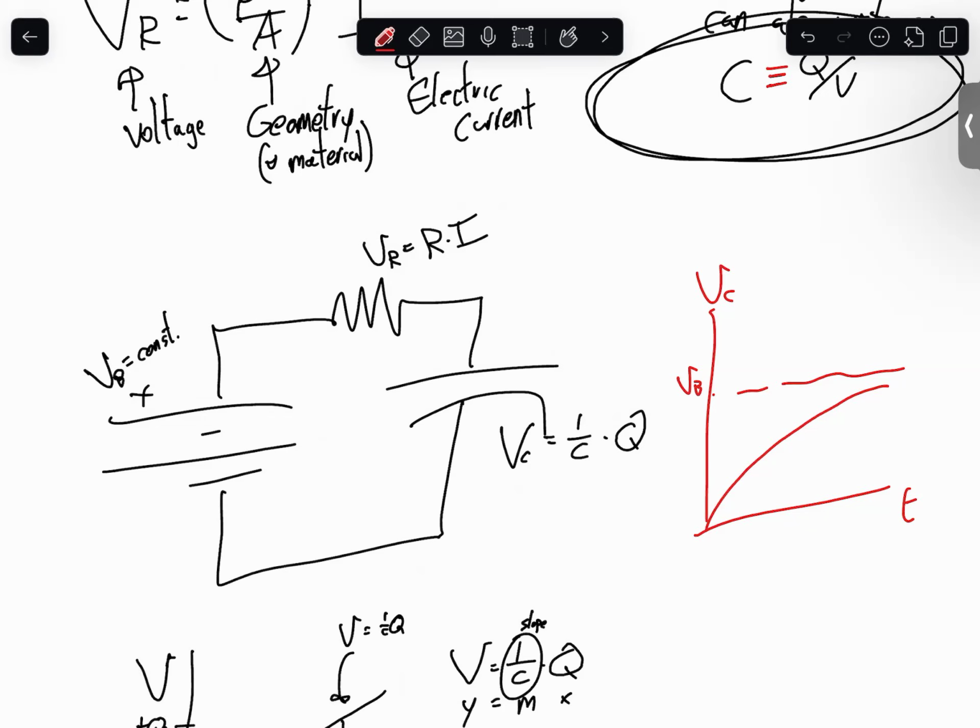This example is what happens if I apply just a single switched DC signal to this. If you've got DC plus alternating current steadily flowing along, the capacitor reaches its equilibrium charge and then just supplies what the input doesn't. This is different. This is switching on DC.